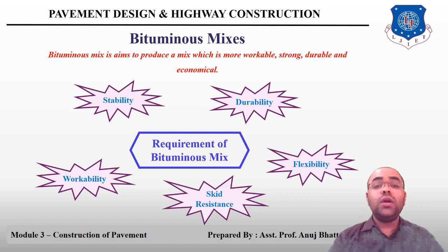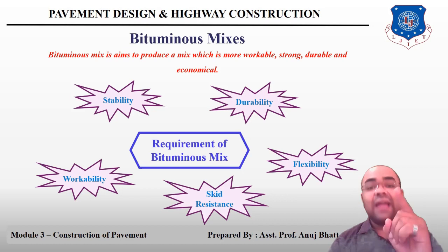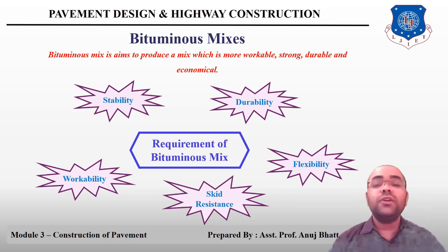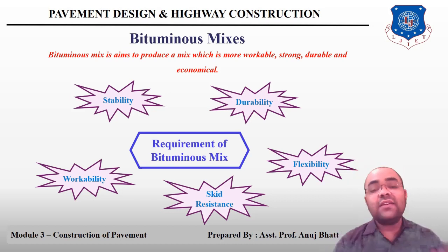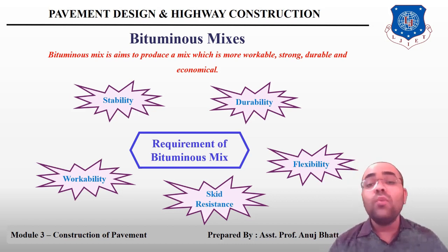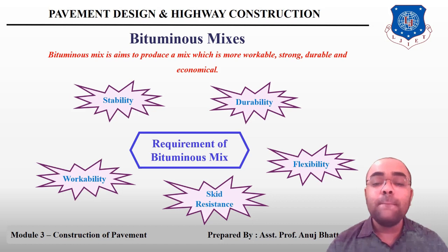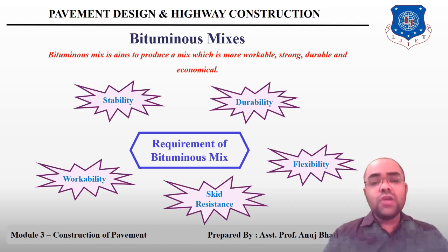This depends on the gradation of aggregates, their shape and texture. It also depends on the bitumen content and the type of bitumen you are using. If we talk about the aggregate, then rounded aggregates improve the workability of the mix. So this was all about the requirements of the bituminous mix.